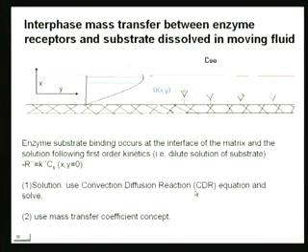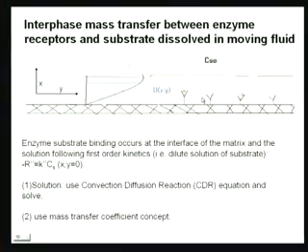The problem with solving it is it's a little complicated, and there are solutions possible for it, but it's slightly complicated. The other option is the mass transfer coefficient. So we can use a mass transfer coefficient. If you know what the mass transfer rate is from the fluid to the solid, then you can use a mass transfer coefficient, and in that case what would be your basic concept? At any point of time, what are the two rates that are equal at the interface?